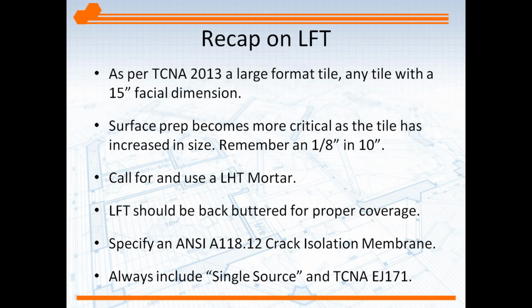Always include single source. Single source is going to get you that literally free warranty from the setting materials manufacturer. We all have them, whatever your choice of setting materials. If you list all the products, or if you're a contractor, if you use all the products from that company, you're going to receive a longer warranty for your client, and it's free just for using all those products. And of course, TCNA EJ171, critical for tile installations. That's all your soft placements of joints and movement joints.